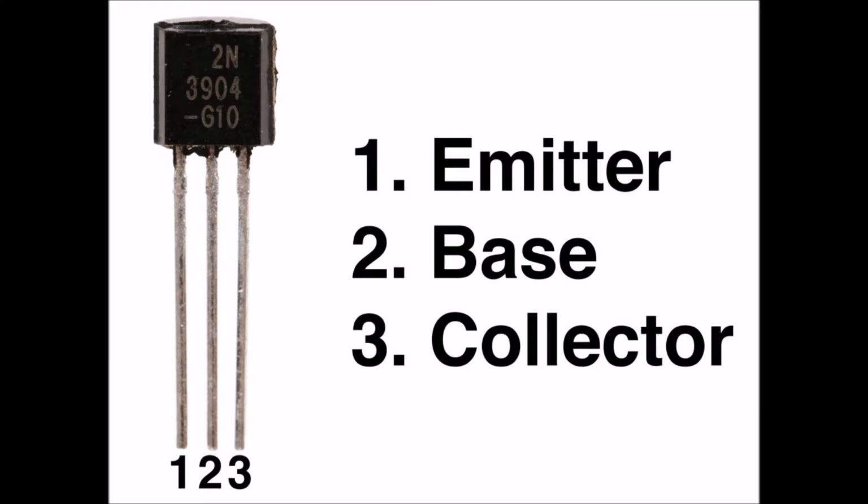The DC bias is the same as that for the common emitter circuit, but we apply the input signal at the emitter instead of at the base. This arrangement gives rise to fluctuations in the voltage across resistor R1, causing variations in base current. These small current fluctuations produce large variations in the current through R4. Therefore, amplification occurs. The output wave follows along in phase with the input wave.